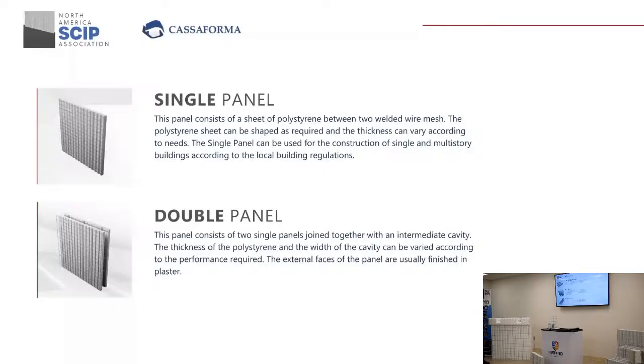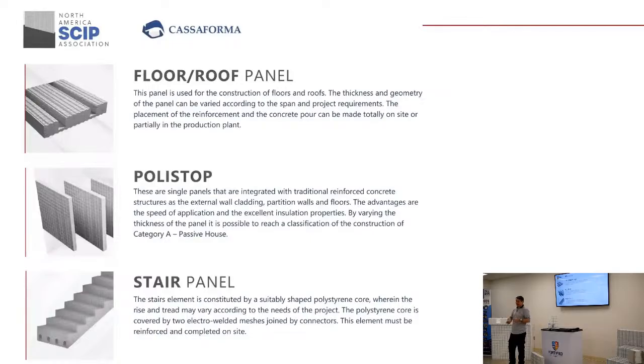So that's the reason why we have this, and there are panels that have 2 pockets, 3 pockets, 4 pockets, up to 6 pockets. Okay? And of course, every time that you have that, two things will happen. One thing, it will get a little bit heavier because every pocket has to be filled with concrete. And the other thing is that it will be more rigid, you will be achieving more stiffness, and of course, the span will be larger. Okay? What span? Well, you probably get up to 32 feet.